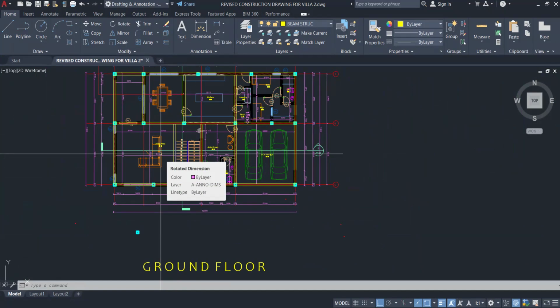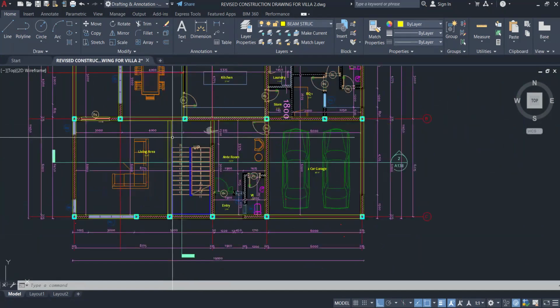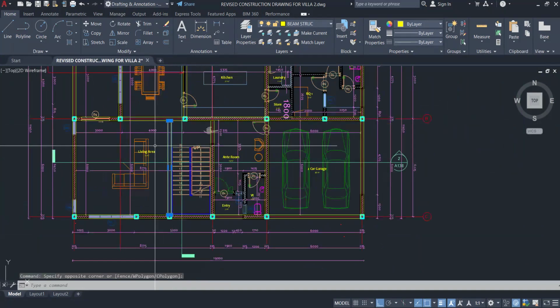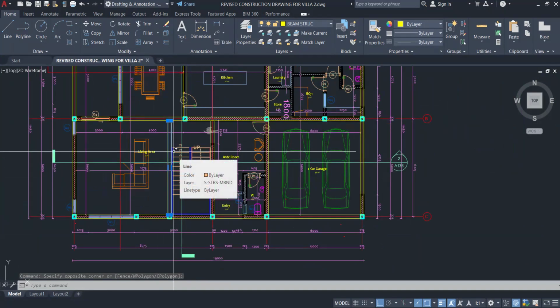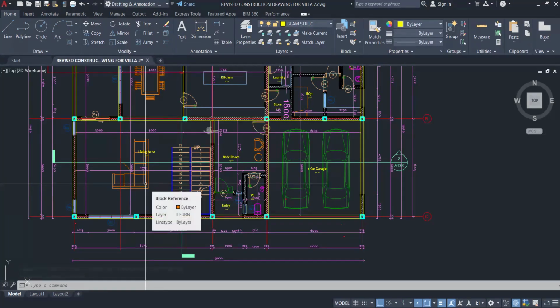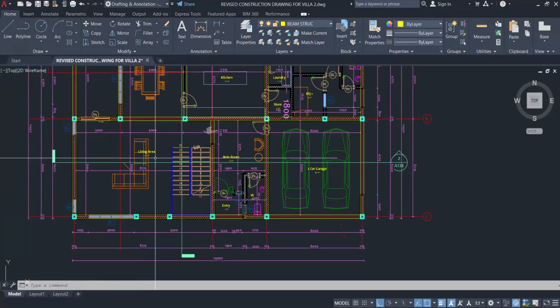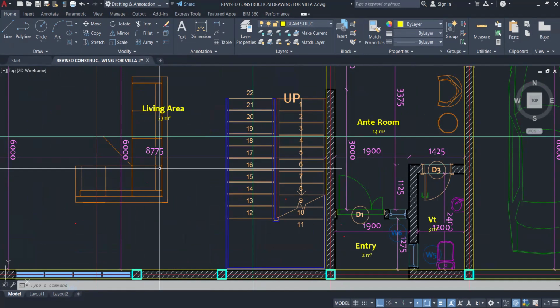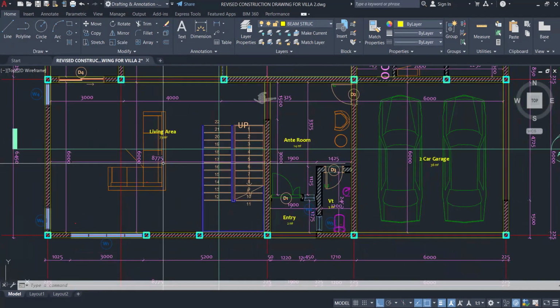Sorry, what's the main reason for putting a barricade between the staircase and the living room? Is there a particular reason? You see now, if I remove that beam, it's not really a barricade, I just use that language. If I remove that beam, you can see that this area is very wide. You see the living room area, it's very wide. So if you want to design it with a 150 slab, it will not pass because it's around 6 meters by 8.7. So it will not pass.